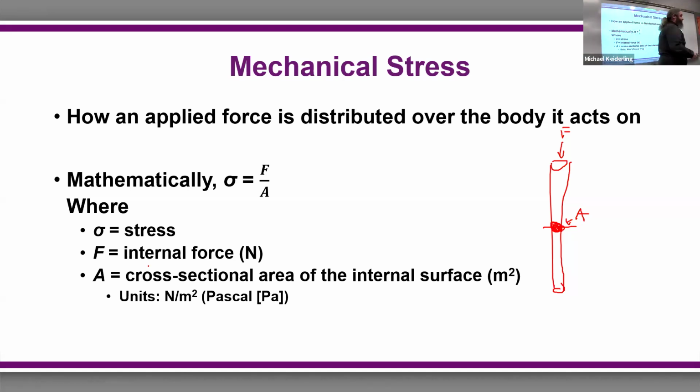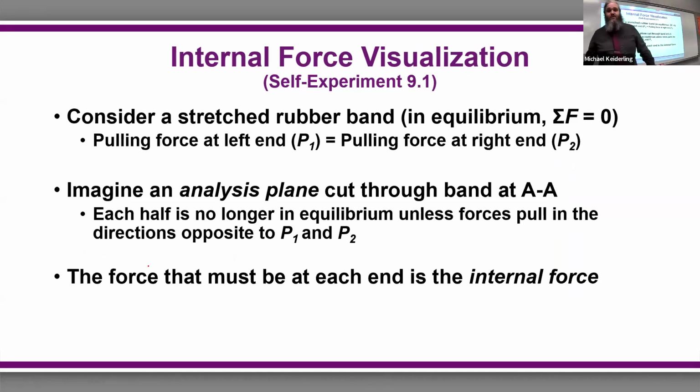So stress is the applied force over the cross-sectional area. So when we talk about the stress on an object, that's what we're talking about. And that stress, when you apply a force on an object, will deform the object, and that deformation is measured with the strain. So let's see if I have something, a rubber band. If you think about a rubber band, consider stretching a stretched rubber band. Let's see if I have a rubber band around here.